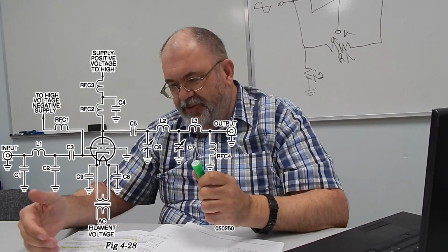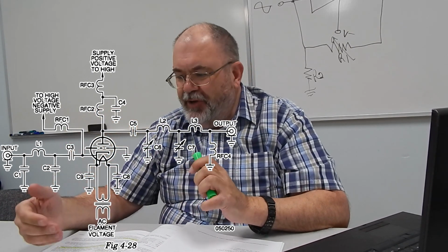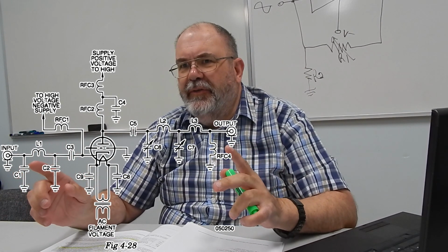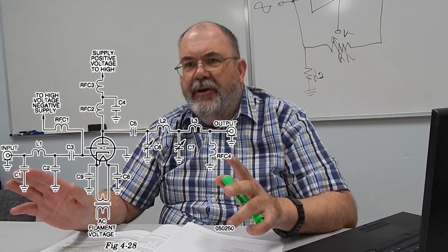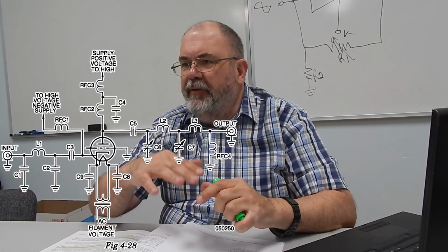Okay, and the problem is that this is an amplifier, and this amplifier is relying on those free electrons being available. So the heater comes on and heats up this plate red hot. This plate is boiling these electrons off. Sounds all fine and dandy. But what happens if the heater is not constant? So the supply of electrons is not constant.